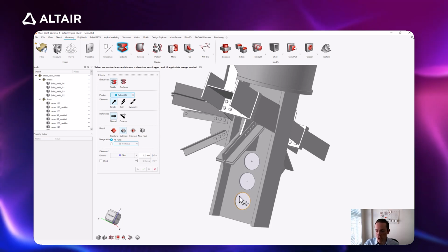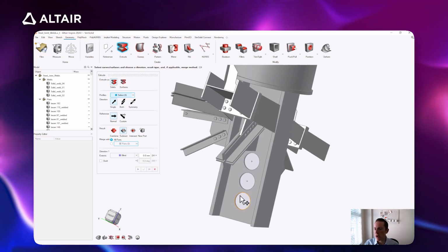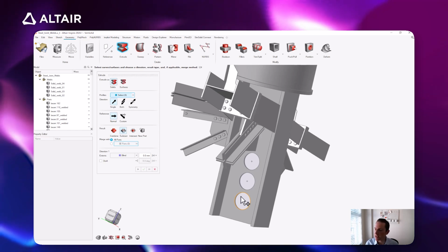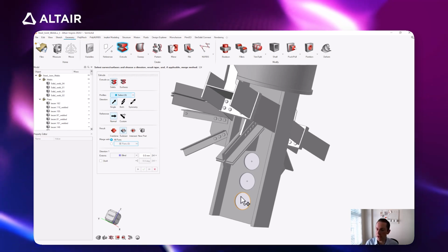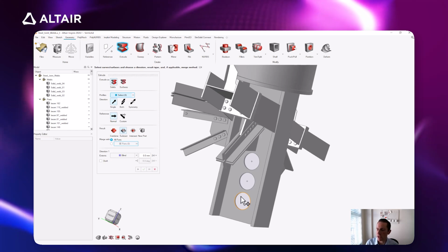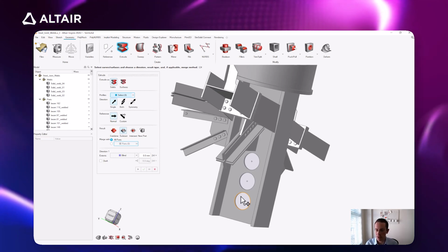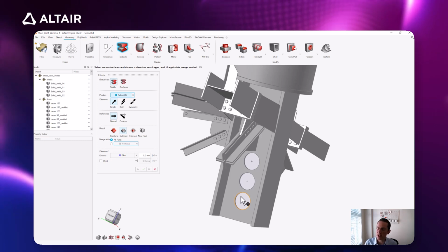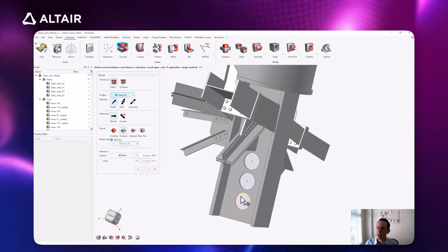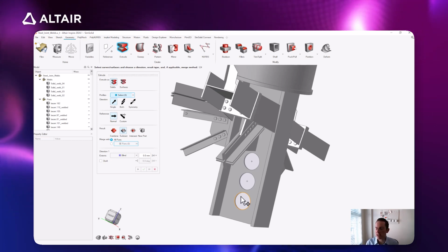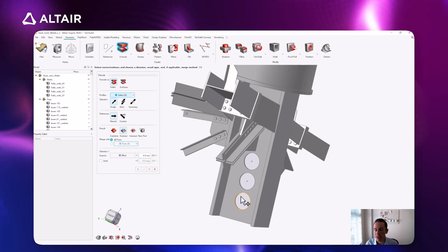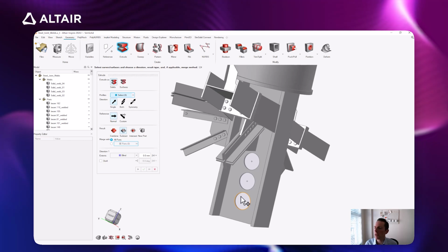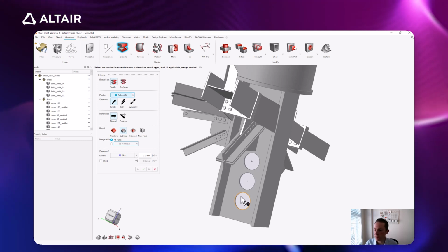And we can parameterize all these geometry inputs as well. So if I wanted to, I could have set up a parameter that defined the radius of each one of these circles, and another parameter to define the spacing between each one of these circles. Perhaps another that defines the positioning. And we can run a design exploration to find the optimal position, radius and spacing of all of these that will reduce the weight, but still make sure that we're beneath our yield stress.